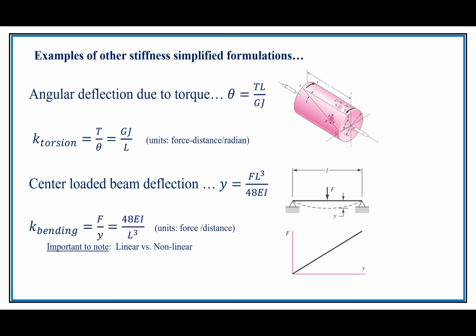Other displacements we might want to consider in the same type of mindset. What we're discussing here really is the step-by-step idea that we're going to create a K matrix, right? Or that someone who has created an FEA code has made an element, and that element has a stiffness matrix or stiffness properties. When we combine a bunch of elements together, we're able to formulate a stiffness matrix.